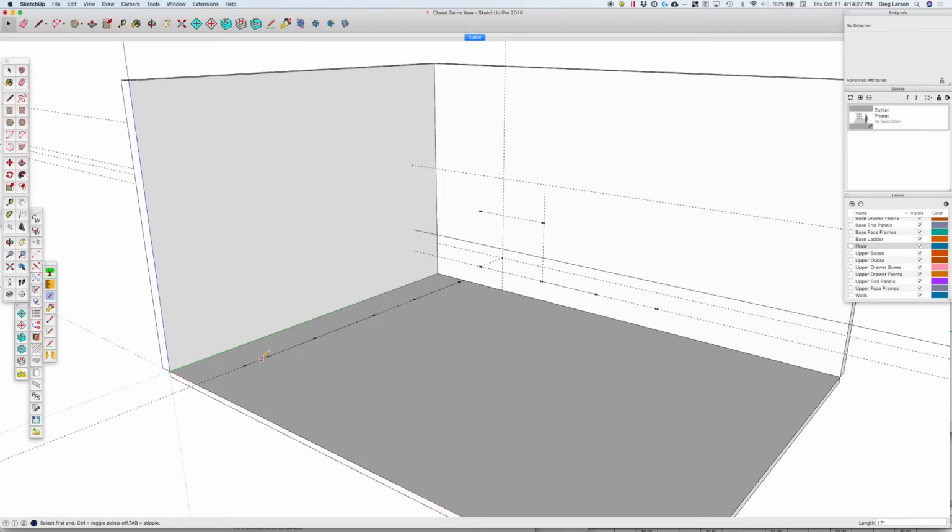So what I did was I laid out the distance for each of these bays, because what I need to do is I got to draw these cabinets individually and overlap their sides and then delete the side of one of the cabinets. Otherwise, CabWriter only knows how to draw a cabinet with two sides, and in this case we need a cabinet, this one with two sides, this one with maybe no sides, so to speak, this one with two sides. I'll show you what I mean here.